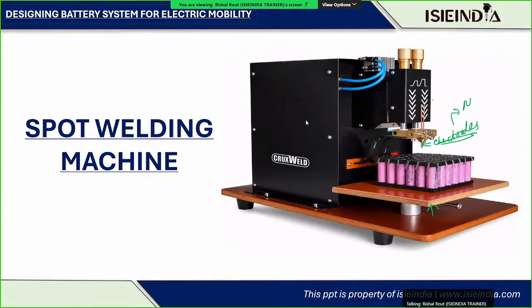This is basically a pneumatic spot welding machine. You can see this is the pressure gauge. You will have a foot pedal. If you press the foot pedal with your leg or toe, this will come down and touch the battery and spot weld the tip. You just have to place the nickel strip above it.